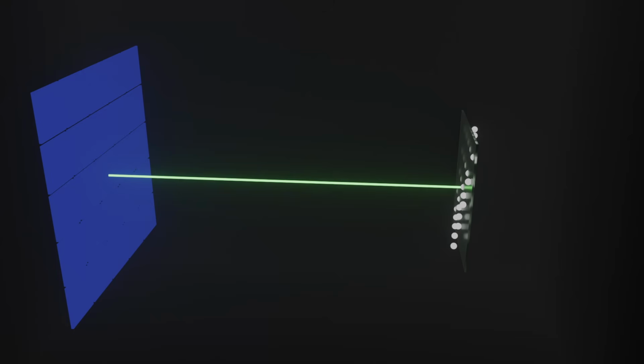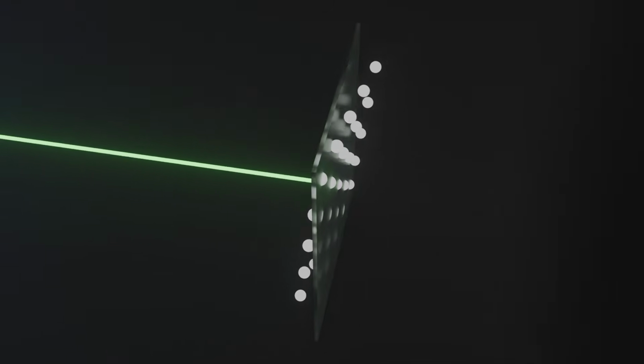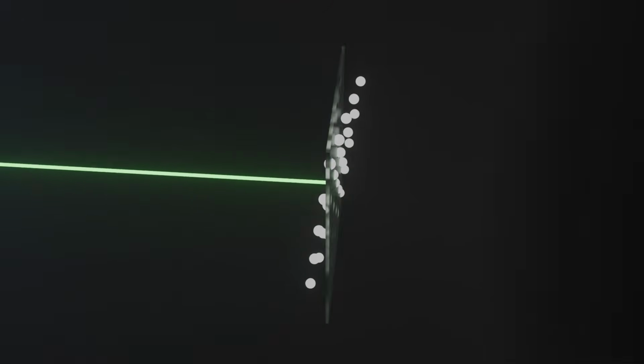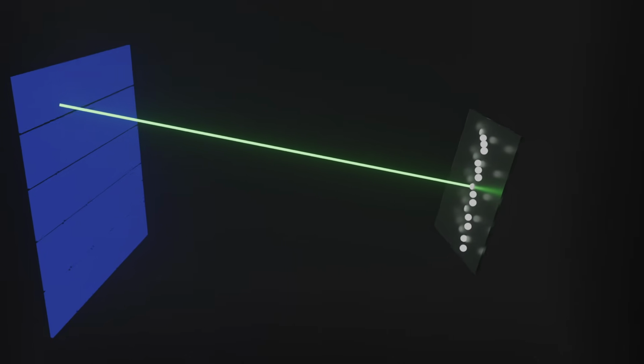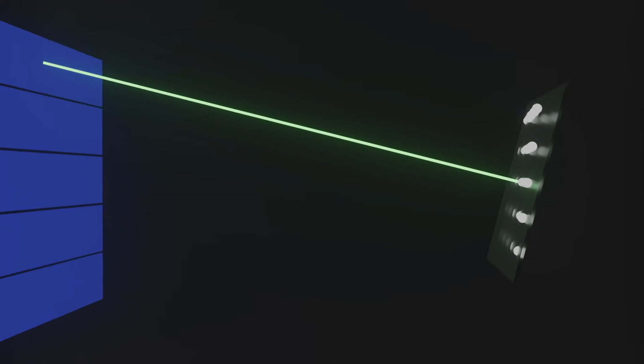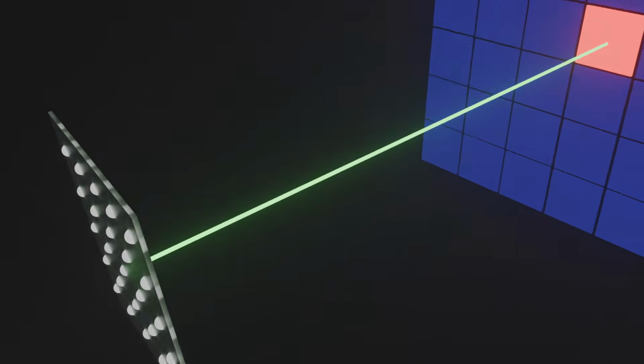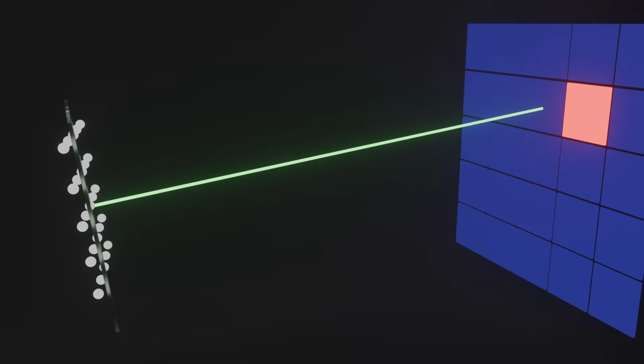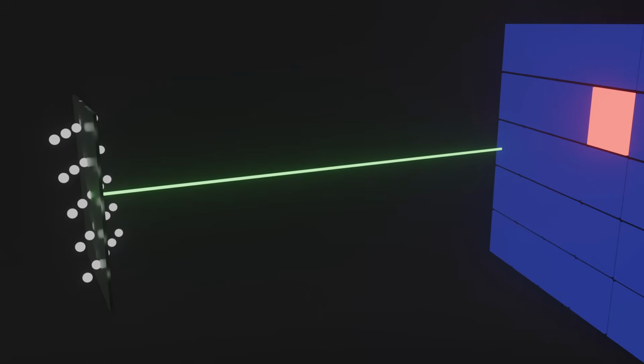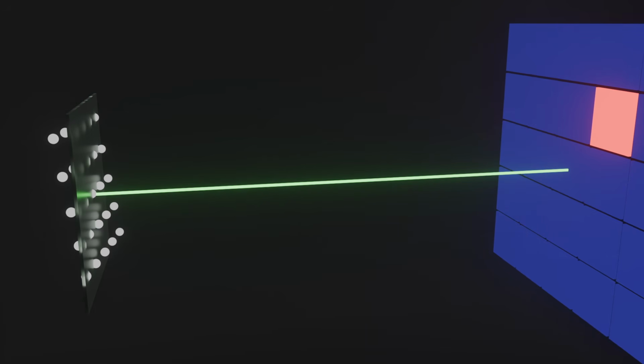Moving this to 3D, I think, makes it a little bit more intuitive. In this render, the white dots are the microphone signals. The plane intersecting with them is our test line. The green line at a right angle to that plane is what points at the pixel that we're testing, and the blue squares are the actual image pixels. For the data being shown here, we should only see a single pixel lit up in the final image. To make that image, we sweep the green line to point at all the different pixels, check if the plane lines up with our data points, and if so, we light up that pixel.